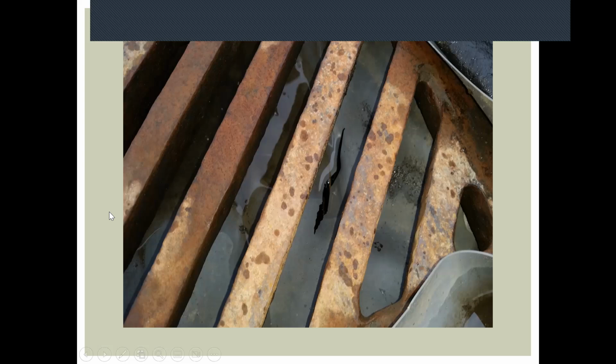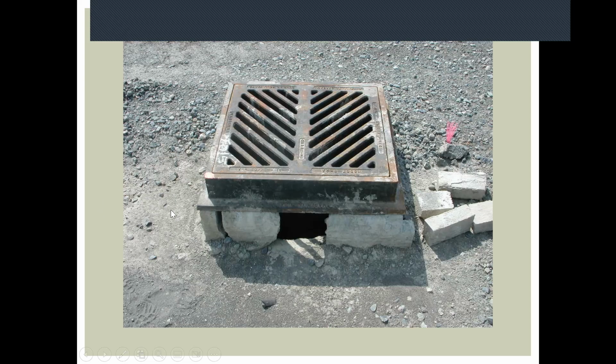If you do put visqueen or PVC or something under a catch basin to keep water from going in, just be aware that people don't like ponded water on their sites, and somebody will go stab a hole or several holes in the plastic and drain it. So that's something to be aware of and to point out to the contractor. It's good that you're keeping water out of the catch basin because it's a live system. It's bad that you're draining it by poking holes. So talk to all your people on site and let them know this is not okay. I think this one goes without further discussion.